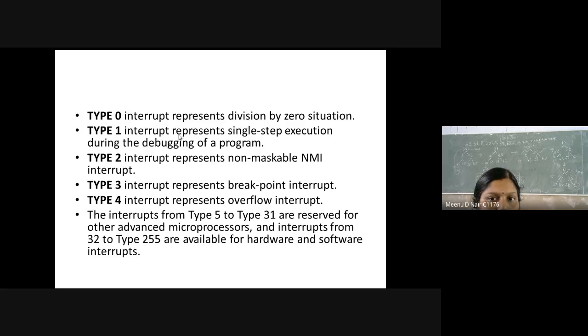Next one is type 1. Type 1 is a single step execution during the debugging of a program. You know about bugging and debugging, right? While debugging a program, it has to execute step by step. That is single step of execution, that is the type 1 interrupt.